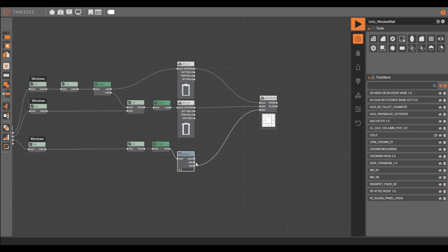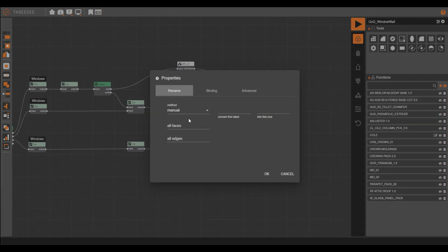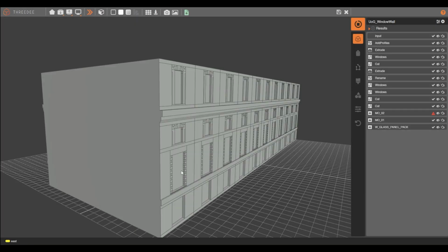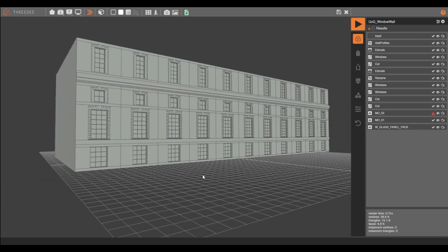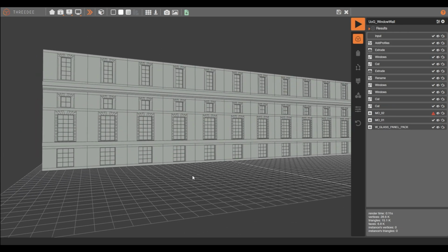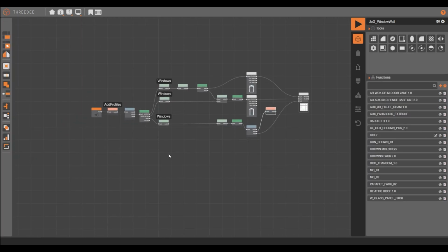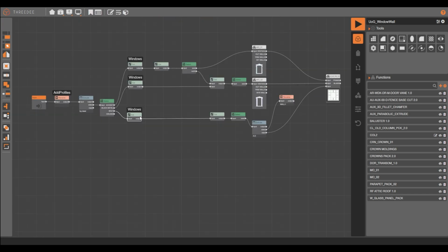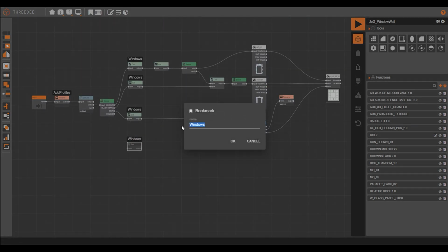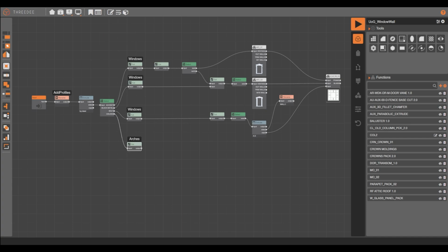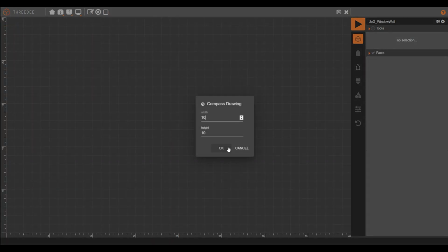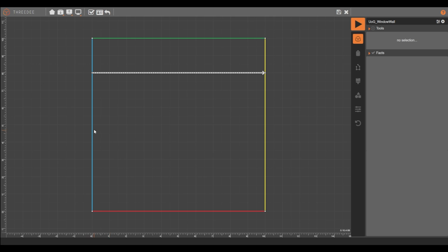After duplicating the first 3 nodes of the last section, we will create an extrude node by an amount of -0.3. We will connect the caps to our window function and rename the sides to wall 1. For the last section of the building, we will duplicate the first cut node once again, and instead of windows, we will just rename it as arches this time.